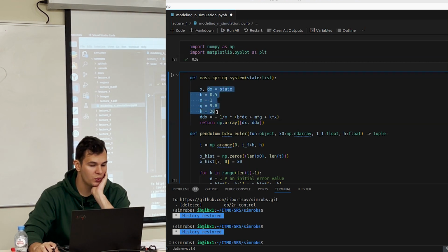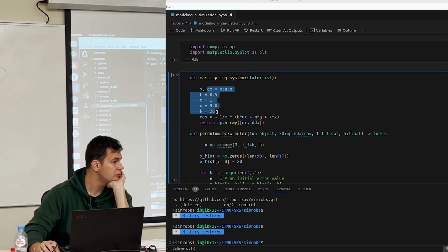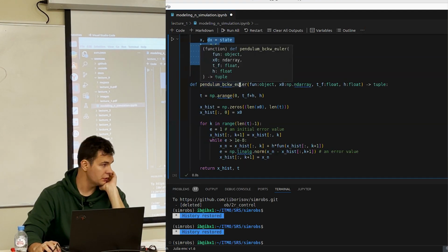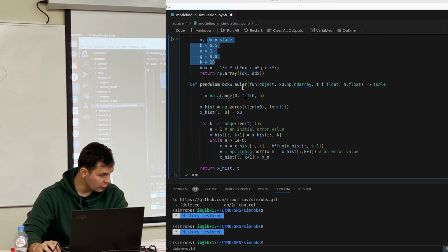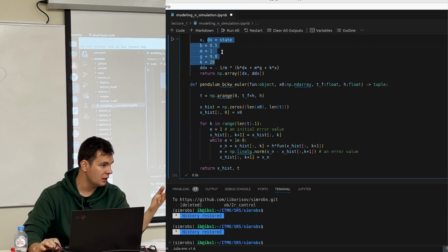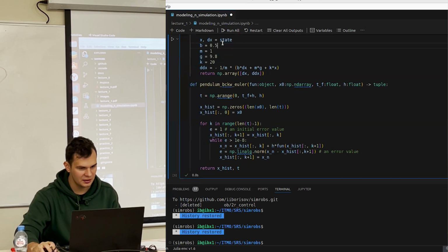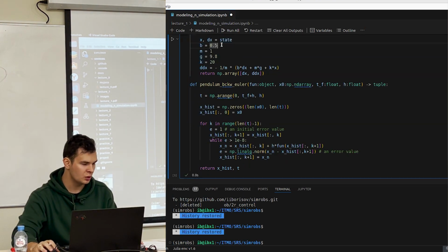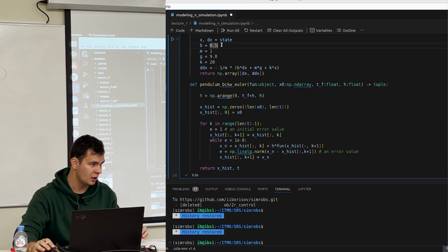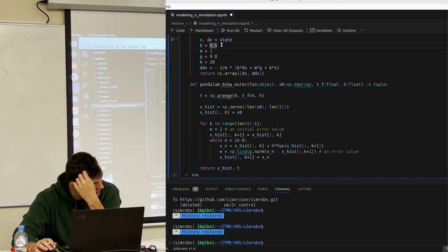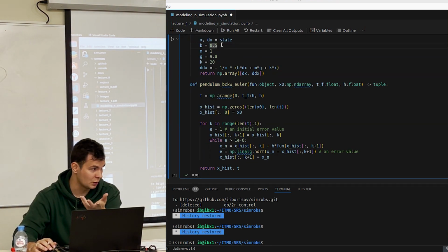And you can play with the different coefficients. For example, instead of backward Euler, you can try forward Euler. You can disable, for example, damping, and your system will blow up. If you add damping as it is here, it's going to work. It just depends on the time step. So you can come up with some time step that works. Okay.